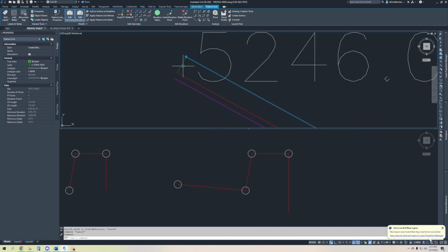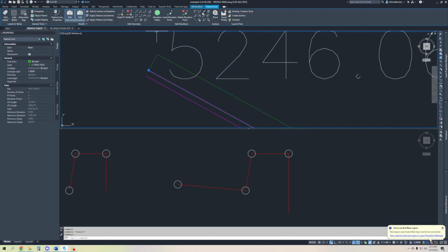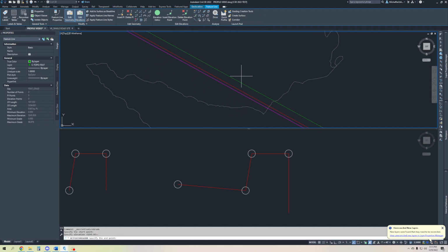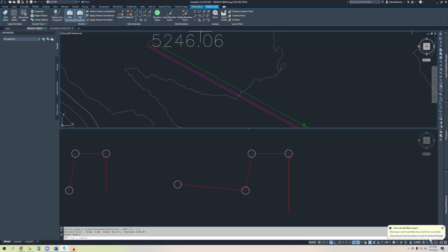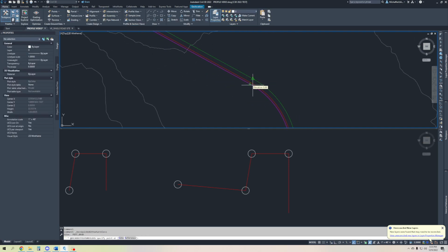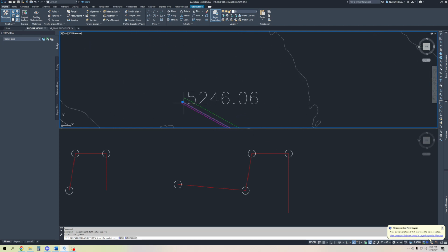So now that I have this drawn, again, I know elevation between points. I have that elevation, and I'll select here. I know I had the lip of my gutter at minus 1.5%. Hit enter, and now using Quick Elevation Editor, I know it's minus 1.5%. That point there, if I were to draw a line and a feature line there, it would more than likely end up being close to minus 8.83%.